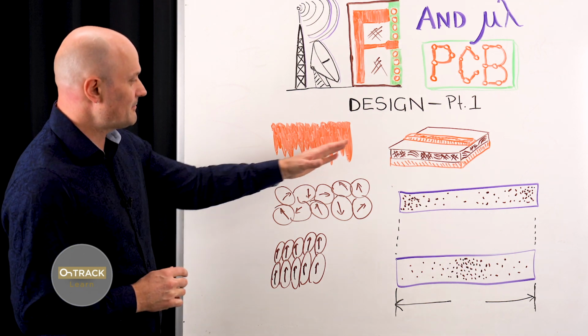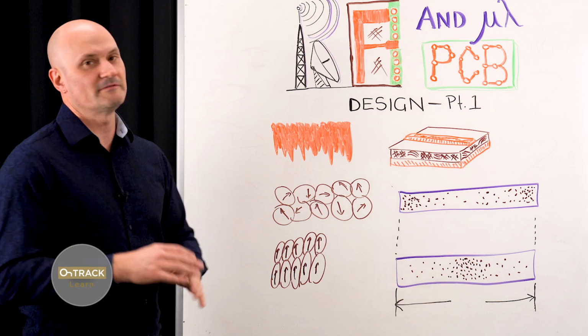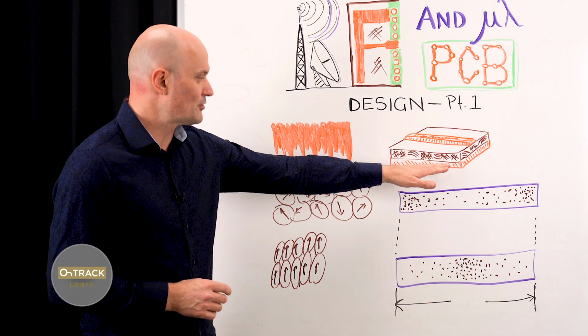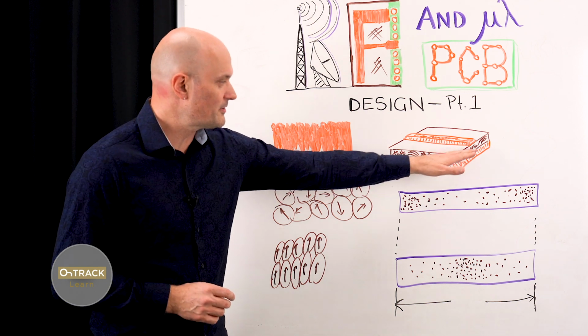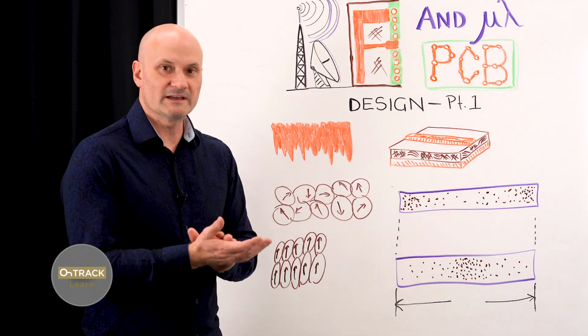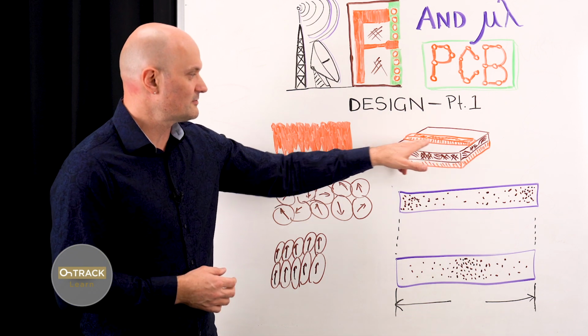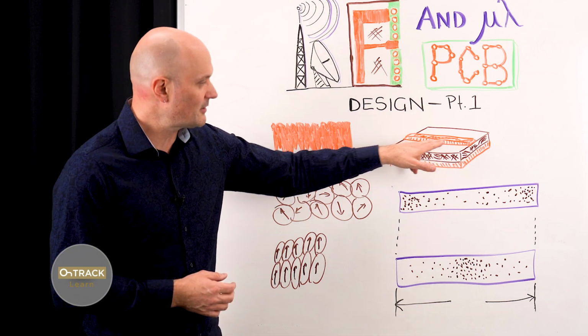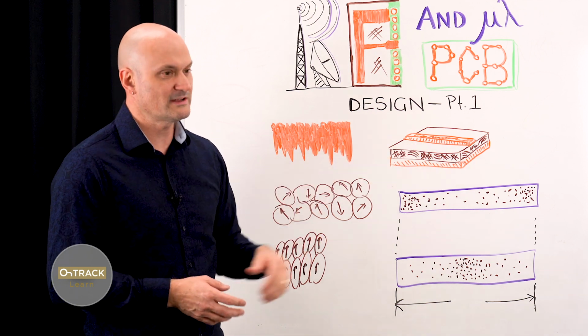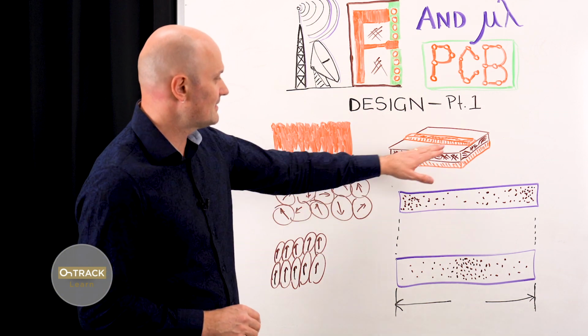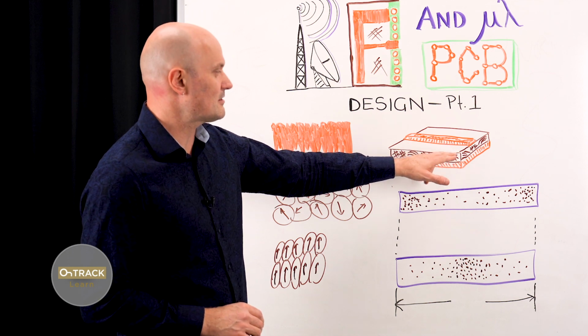I've got a little example here of a section of PCB substrate, and you'll note I've drawn it with some copper on the bottom there. That's effectively a copper plane. That's a reference plane, and a microstrip line trace on the top. This is pretty typical of any PCB trace. And they're connected to each other through the substrate.